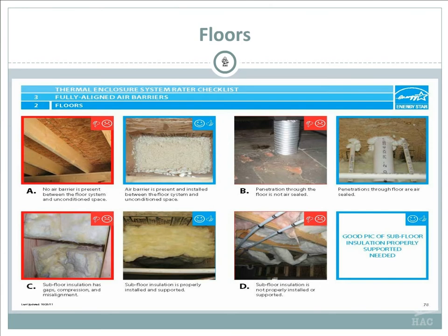Let's see. The one on the right, like I say, is basically how the insulation is going to end up after about 4 or 5 years if nobody's gone down there and kept it up. The next time the rater or somebody goes in there looking at the crawl space, the tiger teeth have fallen, the insulation has fallen, all these voids are in place, and you can see where it's coming down. On the right side, we don't have a good picture of that, but it should look something like the one to the left. And it should be that way all the way around.